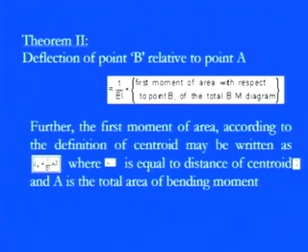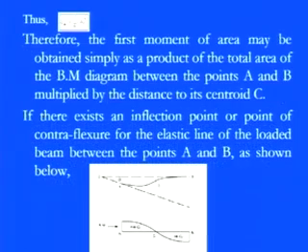Once you have the centroid position, once you have the area, and once you know which material the beam is made of and what the cross-sectional area is, you can simply get the deflection for any kind of beam, or whatever the kind of loading is. So with the deflection described in terms of the centroidal part, if we have a centroid in this particular beam's bending moment diagram, we can simply calculate delta A, which we discussed is nothing but equal to A x bar divided by EI.